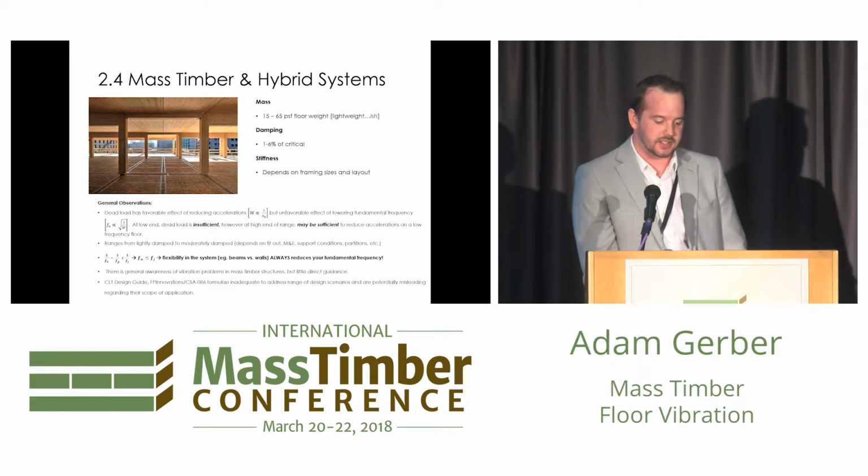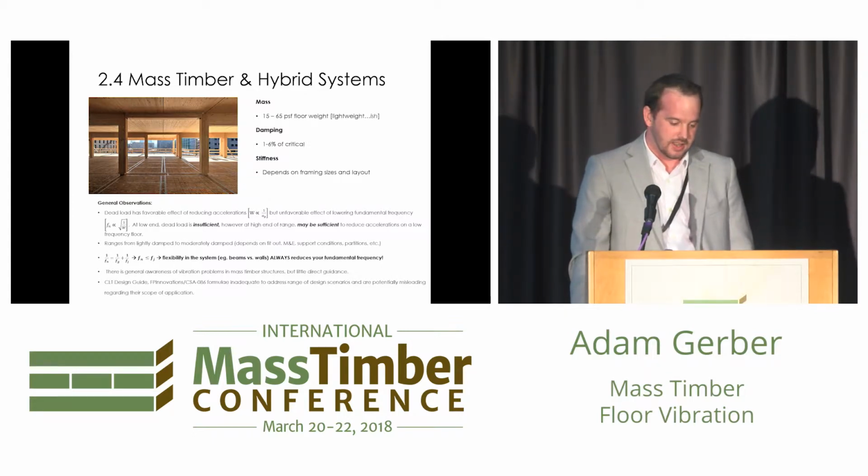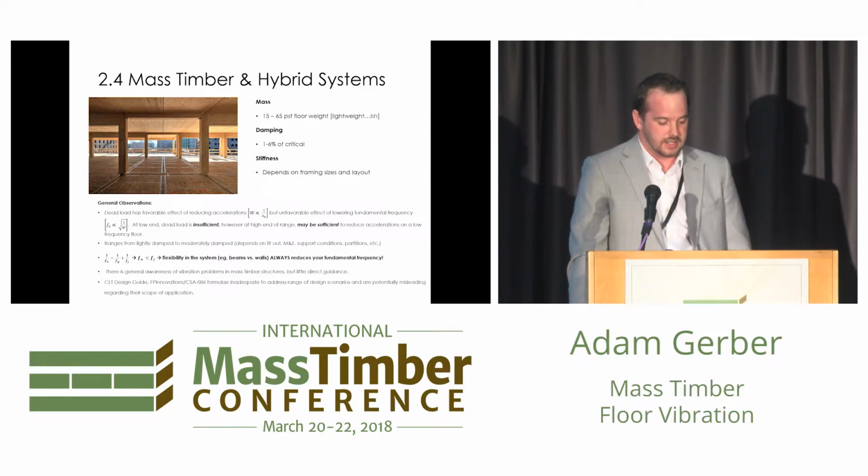In terms of mass, we're more like 15 on the low end to sort of 65 pounds a square foot for floor weight on the high end. So sort of lightweight-ish. Damping between 1 and 6%, pretty typical of the other systems as well. And the stiffness, again, really depends on the framing size and the layout.